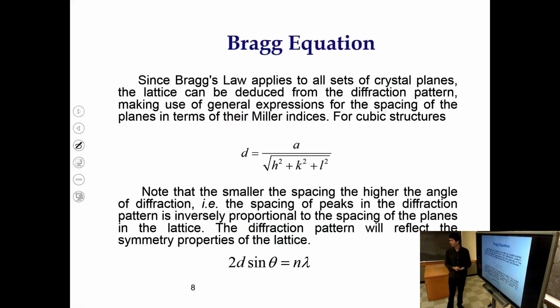And this is true. So last week we calculated the spacing between planes, and we have these formulas. So you can see that d, this is something that we can extract from the X-ray data, the spacing between a family of lattice planes that gives a strong X-ray resonance. And it's inversely proportional to the square root of h squared plus k squared plus l squared, where these are the Miller indices of the particular planes. And of course, the crystal lattice constant for the material is also here, scaling everything. So this is, of course, only for cubic structures. We can write this formula for other structures, obviously, but we limit ourselves here to the cubic structures. So this is why larger Miller indices will give you smaller d's. And look back to the picture from the previous slide to visualize why that is the case.